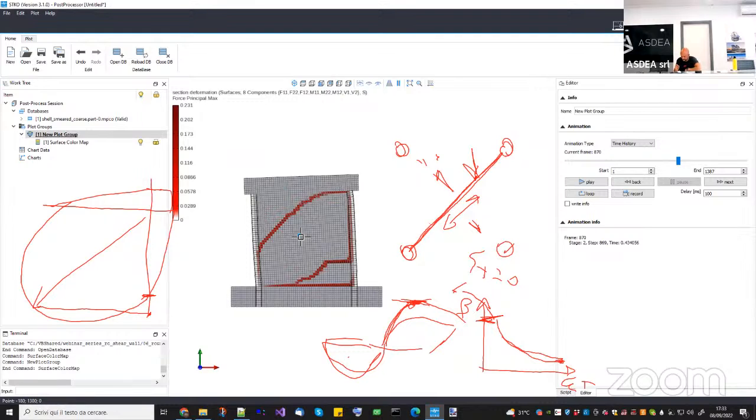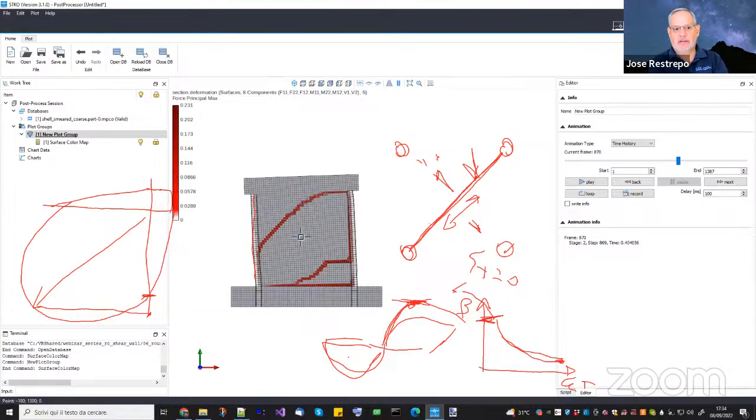For the user, if you want, for example, to model the boundary beams, in my case I did it with beam elements, but if you want to do them with the beam truss element, you should take into account the confinement before you define a modified constitutive model. Yeah. Which is basically actually what we do in beam elements. But that's typically done for the vertical elements, not for the diagonals. So the diagonals are considered to be unconfined, and they will only go down in strength as your strain field transverse to the element increases in tension.